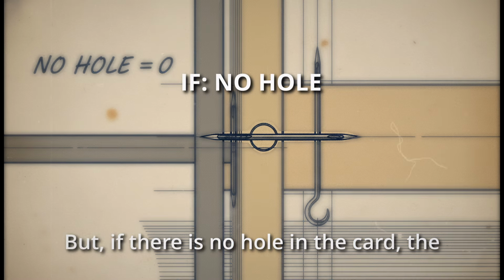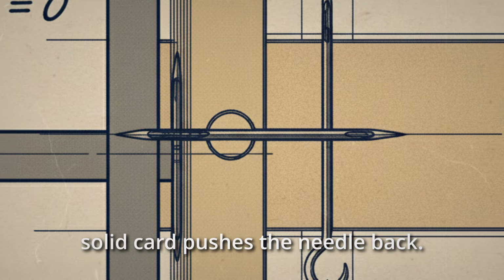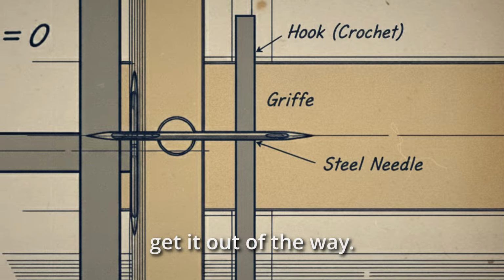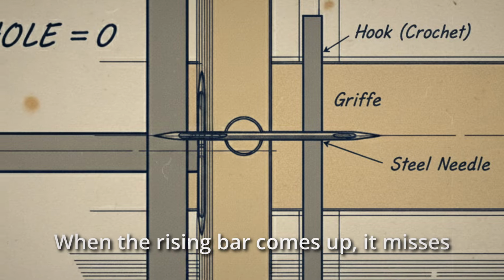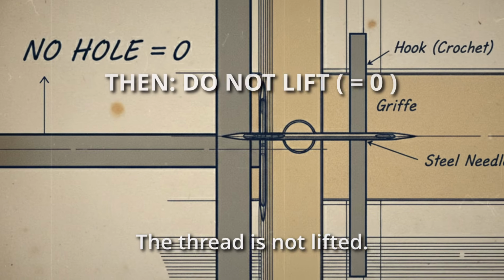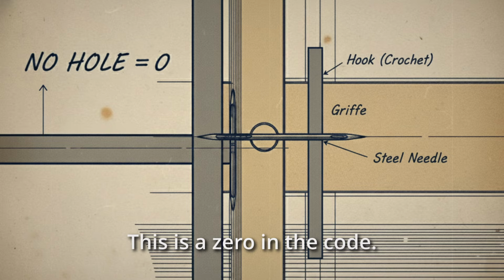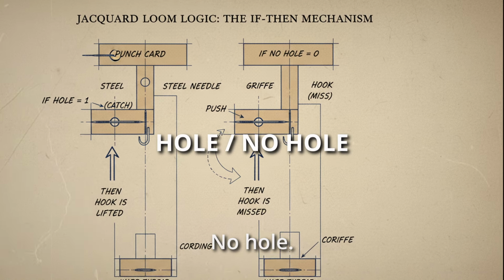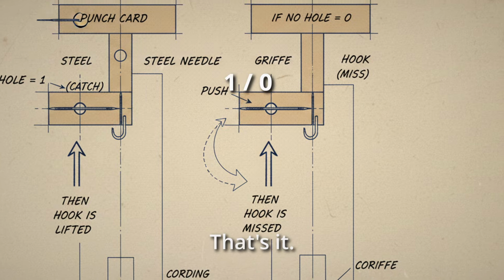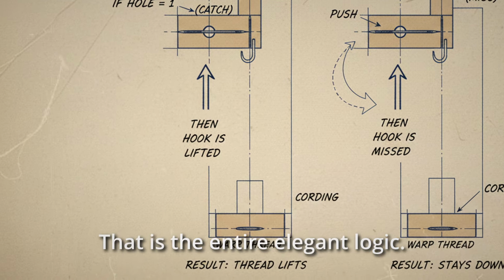But if there is no hole in the card, the solid card pushes the needle back. This push moves the hook just enough to get it out of the way. When the rising bar comes up, it misses the hook completely. The thread is not lifted. This is a 0 in the code. Hole, no hole. Lift, don't lift. 1, 0. That's it. That is the entire elegant logic.